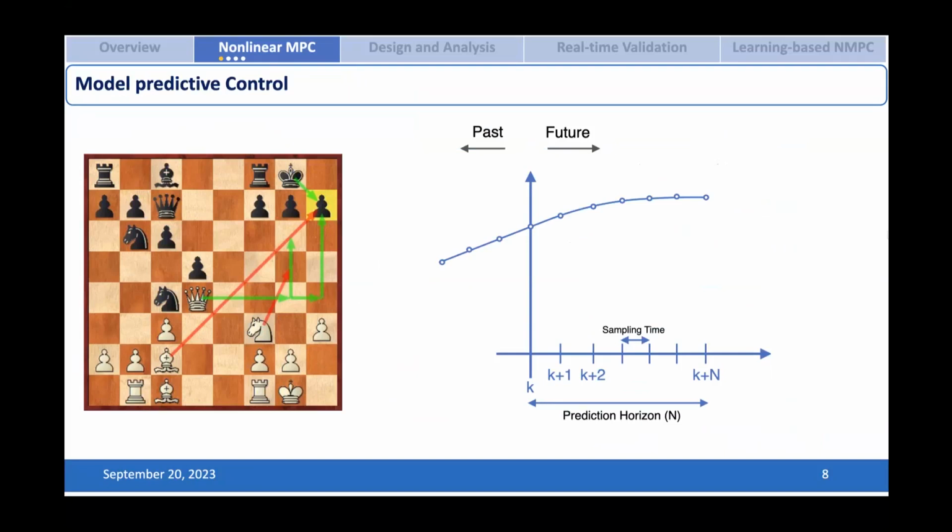Okay, so in this case, we have this reference trajectory that we would like to follow. And the MPC plans ahead in its mind, it plans the open loop input. So it says that if we apply this open loop input, we should find that the trajectory of the system, or the predicted state, should converge with the reference trajectory at some point. So this is hopefully the plan that we are making.